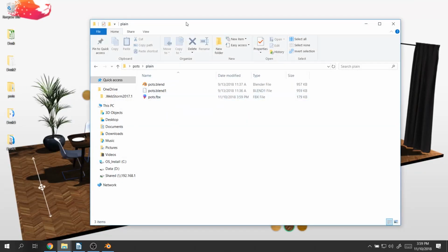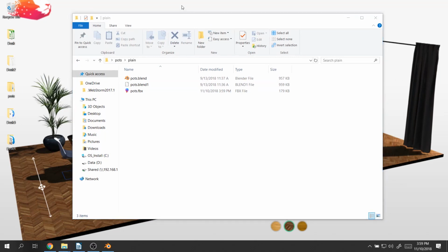And if you're using CAD drawing software, a lot of times you're also able to export to a triangulated format or a 3D format like OBJ, Collada. Preferably you need to export it to a model that keeps the model hierarchy or the model tree intact. If that's not possible, it's also not a problem because you can do all of these groupings inside the Expivi platform as well.